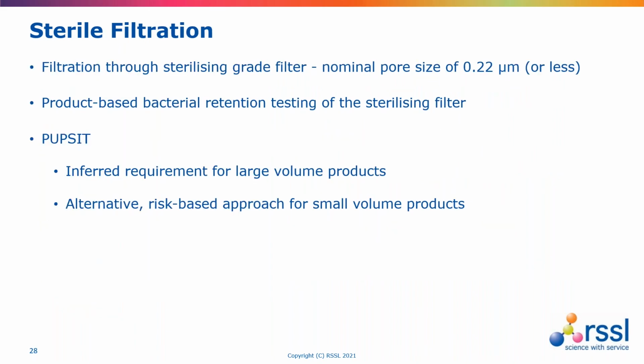With sterile filtration, the PUPSIT requirement is fairly strongly embedded. That's the pre-use post-sterilization integrity testing. There's been a little bit of softening between the earlier draft of the Annex and what is currently in front of us.